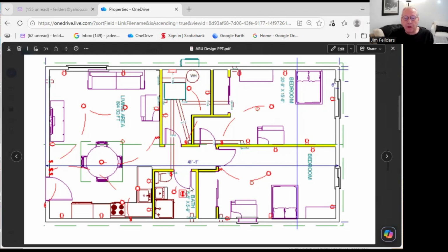And the bathroom, we're showing an exhaust fan now, but we're proposing to replace that with through the wall ERVs. They come in pairs. They're ductless. There's one in the bathroom exterior wall, and then one in the living dining area to provide fresh air through that part of the house.